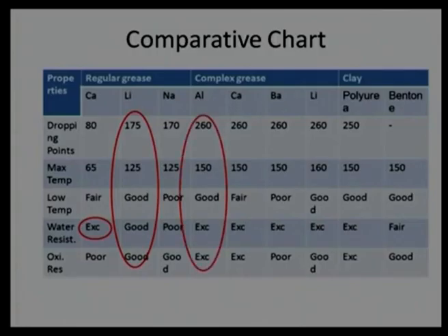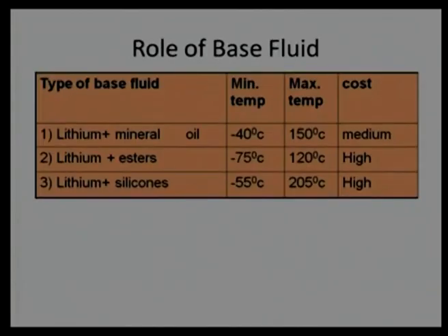When coming to the complex greases, we can find all good performance from aluminum based greases or lithium based greases, but lithium complex will be costlier compared to the simple lithium greases. So, unless it is really required, we should not use it.